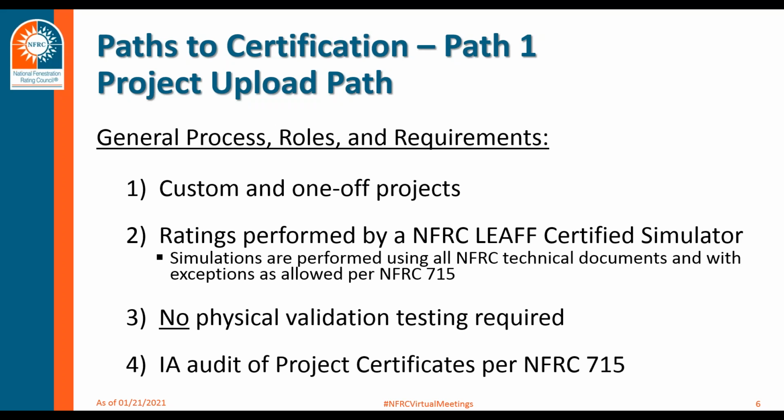This path follows traditional simulation methods for product rating, such as using NFRC approved software, like as today with the LBNL WINDOW and THERM, to calculate the product ratings and applying area weighting techniques as appropriate for the project. NFRC standard configurations, the standard size configurations, do not apply in this path, as this analysis may incorporate mullion and composite assemblies in the project certificate. So think a facade-focused type analysis.